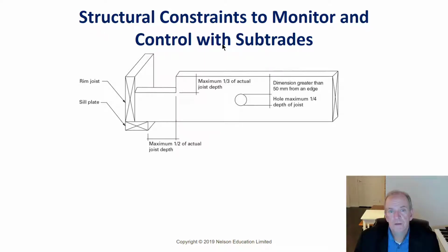Speaking of compromising the various systems, we have to make sure too, because plumbing trades need to run pipes through joists, and your electricians have to drill holes, and HVAC subcontractors have to run ductwork. So we have to consider the framing layout, and that's why you want to have a pre-construction meeting, so that if there's any special things that need to be framed for early on, it's a lot easier to do it beforehand than afterwards.